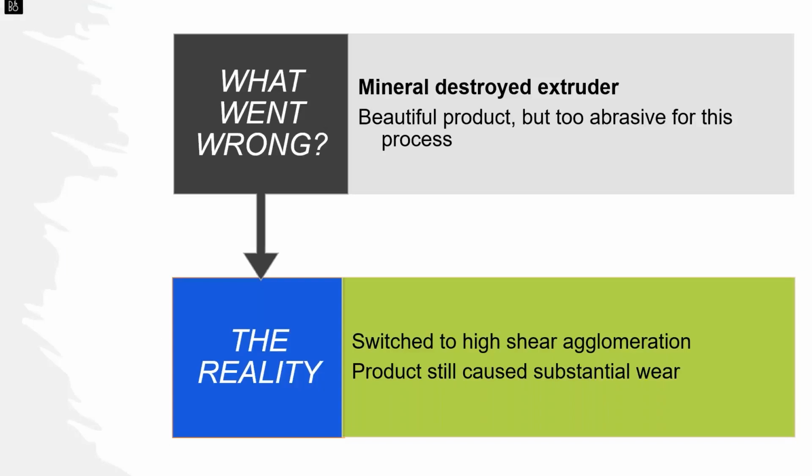But this one is truly a what-went-wrong. That mineral that we used absolutely destroyed the extruder. We ran for about a day and there was no extruder left. It destroyed the screen, it destroyed the flights. We had to rebuild the extruder.